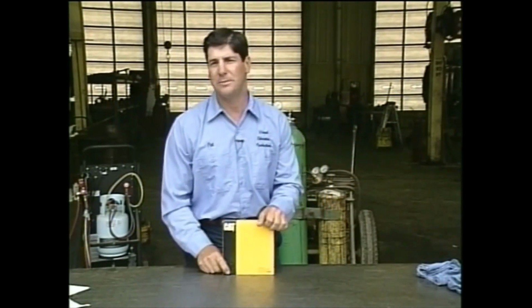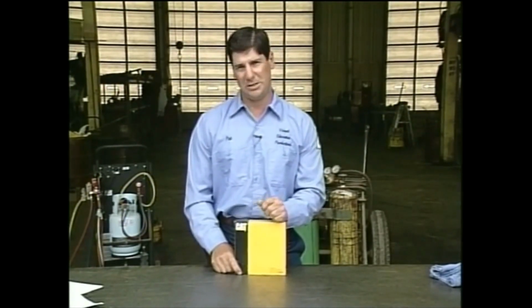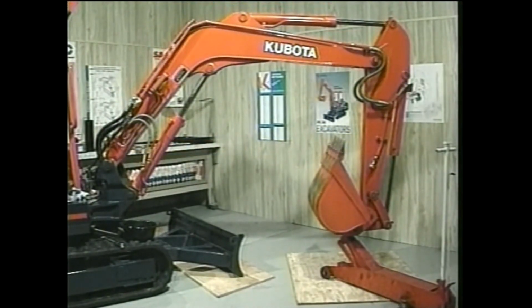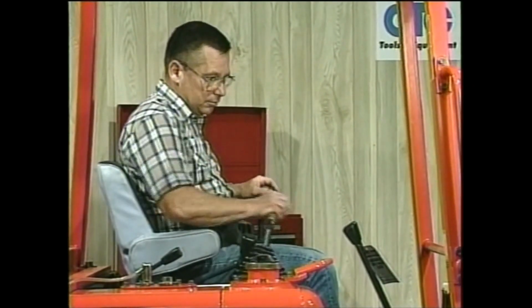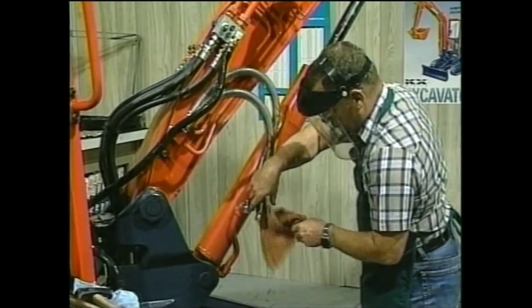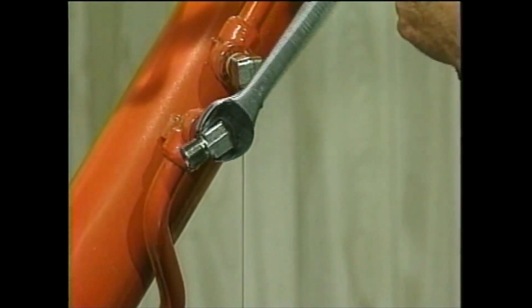There is a common myth that needs to be clarified about leaking cylinder seals. The general belief is that a load will settle if the cylinder piston seals leak. As discussed earlier, even if the piston seals are removed, a load will not settle. To illustrate this point, let's use an excavator with a heavy boom and dipper arm. Before disassembling, all hydraulic pressure trapped in the hydraulic system is neutralized. The hoses are loosened and removed. The oil is carefully caught in a container. The fitting is redirected to drain the oil into the container.